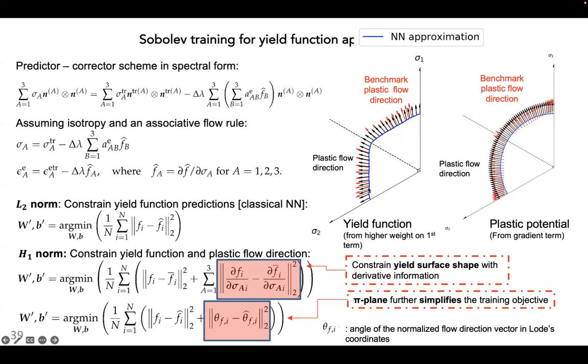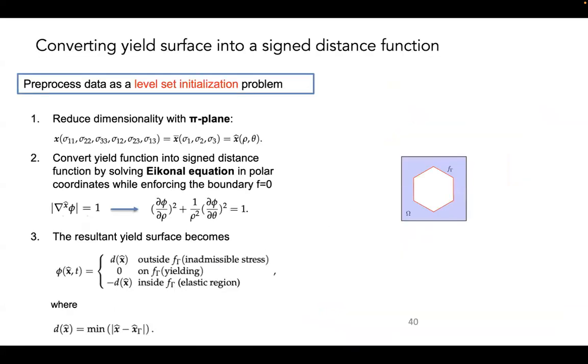If you change the plastic flow, you may want to change the yield surface first, and then use the yield surface as the initial learned function to get the plastic flow, other than changing it with an arbitrary shape. Because the plastic flow has one problem: you only get the gradient data. You know what I'm saying? From the mathematical world, you would have the scalar value of the plastic potential and the gradient of it, but from the physics world, you only get the gradient. Okay, which could cause some stability issues.